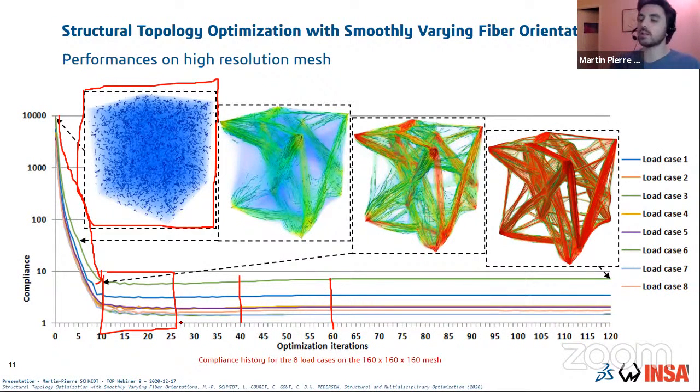After that, the move limits in the optimization are tighter, and the filtering is still acting to smoothen the orientation field. So after this the compliance may be lower, but the orientation field is not necessarily as smooth as you might want it to be. And this is why it increases slightly, and then it settles back again around iteration 50 or somewhere like that.